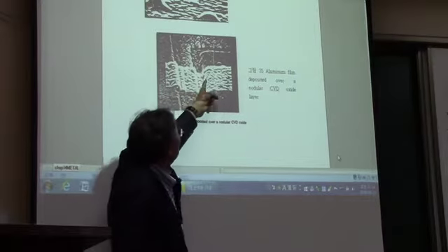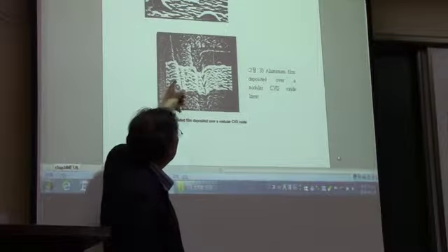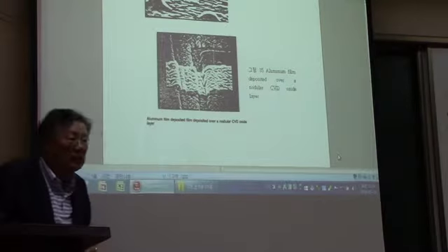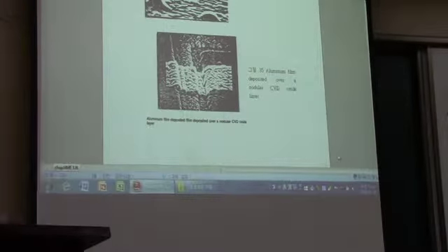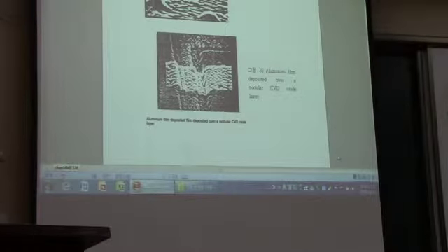This is the metal lines running over different heights of the substrate, and if you form a hillock on the metal lines, then you're going to have a very rough surface, and it is really hard to focus in the lithography, because we are talking about micron size lithography, right? So extrusion and whisker come from the mechanical stress, and the hillock comes from the grain size and grain boundary stuff in the metal lines.